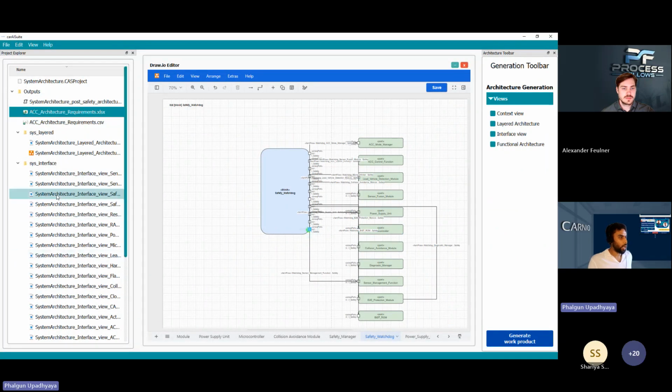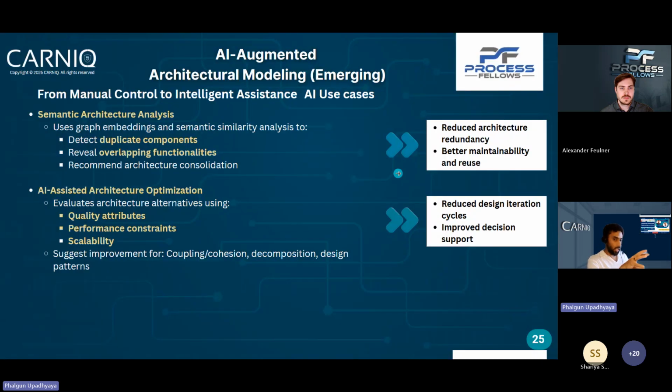So here you can see the different RAM and ROM sections. So this has been identified. But when it comes to the amount of RAM that needs to be present, what the CPU load should be, what controller should be chosen: if you have the microcontroller details added in the requirement itself, these can be identified. If not, the tool also has the capacity to provide such details, like when you have the simulated version, what could be the potential RAM usage, etc. These could be identified, depending on the functionality itself. If the functionality is not yet complete, then these analyses will also not be complete.